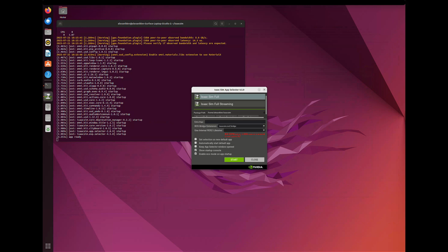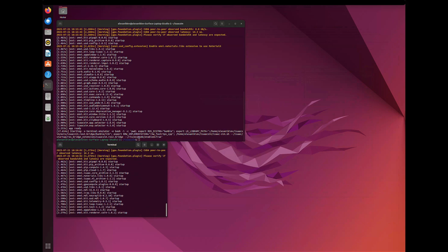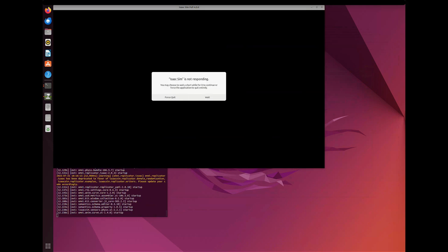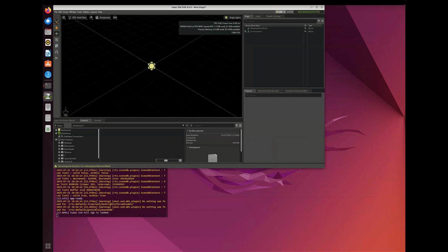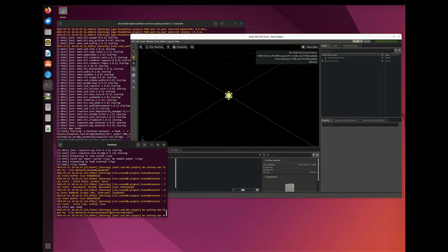When we launch this, supposedly we should load the right rclpy library. But as the output will show, there's one more step required to launch this properly, because the output is still showing that we're using the internal rclpy library, which is good for quick demos, but definitely for our purposes, we want the system ROS2 environment rclpy.